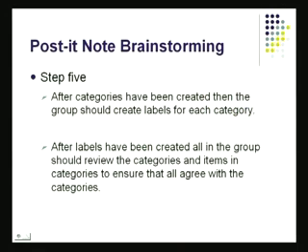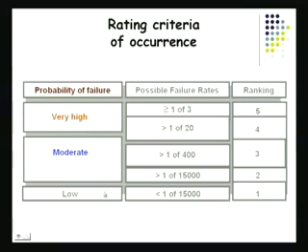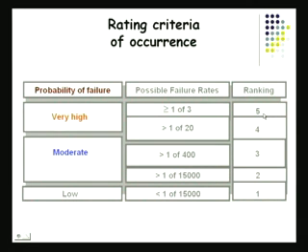If you're now looking for prevention, trying to reduce the occurrence itself, or perhaps the impact of it, if you trace it down to the root, you've got a chance. You've got a good chance there. And so brainstorming would be one great way to get there. Now that will give you the cause. You also have to find out what is the probability that the failure will occur. This is something that can occur at various different places. There could be a very high chance of failure, in which case the chance is something that I have to worry about. So I look at the ranking, and if it is very high, that will lead to a very high RPN, and I want to give it some attention.